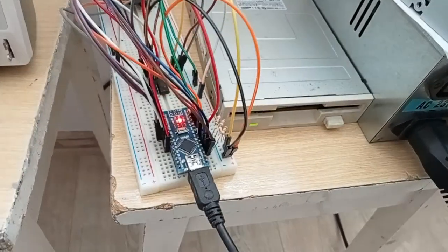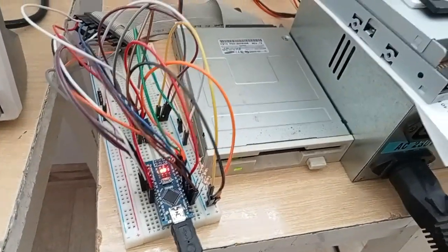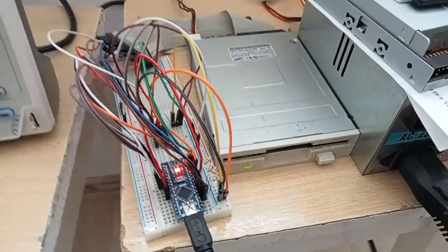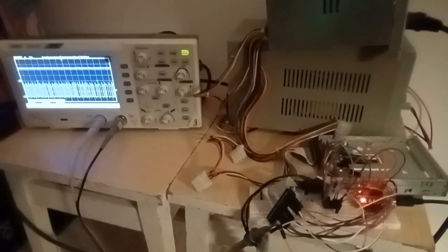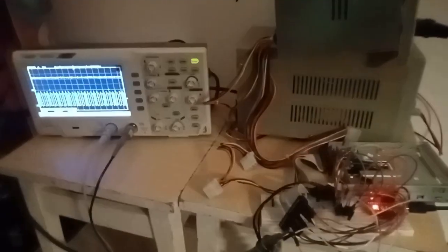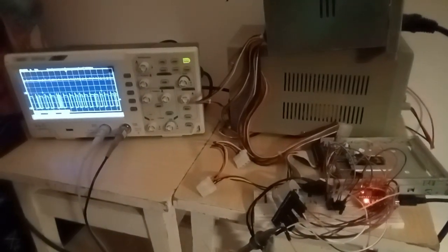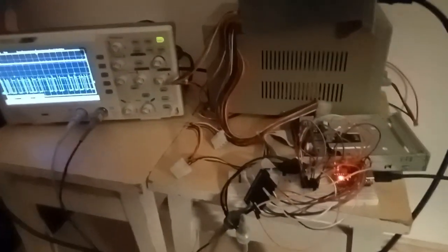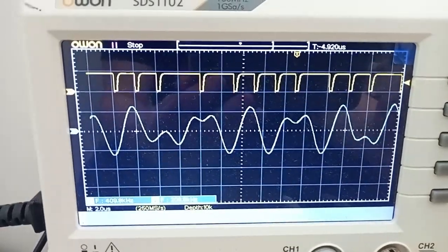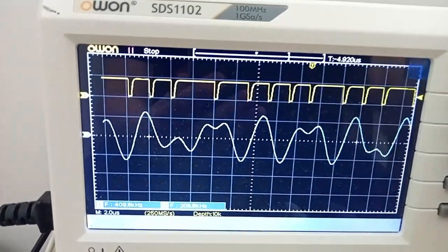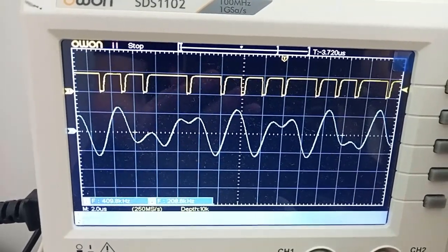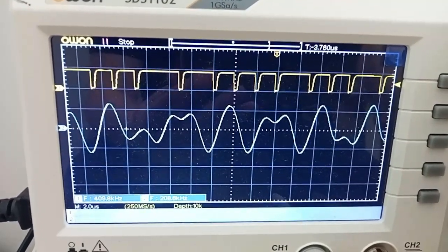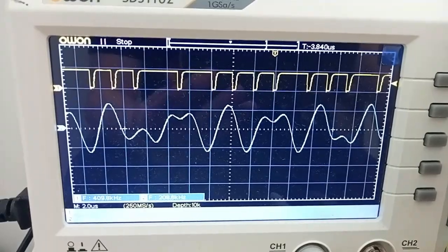This simplifies the read procedure since the microcontroller can measure pulse length on each D flip-flop output state change. Because read pulses are at around 500 kHz frequency, the Arduino does not have much time from pulse to pulse, so some optimization must be implemented to not miss any pulse. My implementation is able to read the time from pulse to pulse, and quantize it to 3 states, long, medium, short, and store that value in a buffer.